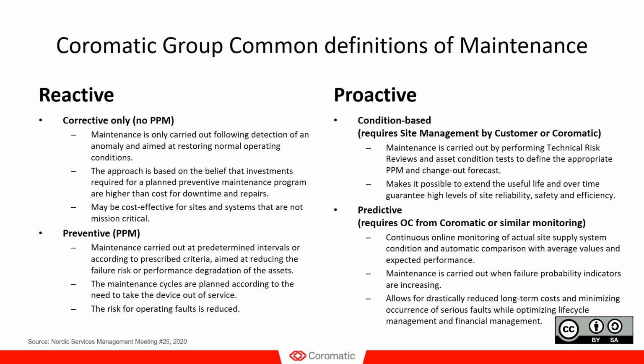The point is that the site management ensures that the asset lists are up to date and that the condition of all site systems and site system components are up to date and reviewed, and thereby you provide a forecast for the exchange of these components. So having an active budget and change out forecasting process for the assets of the site makes it possible to actually have condition-based maintenance.